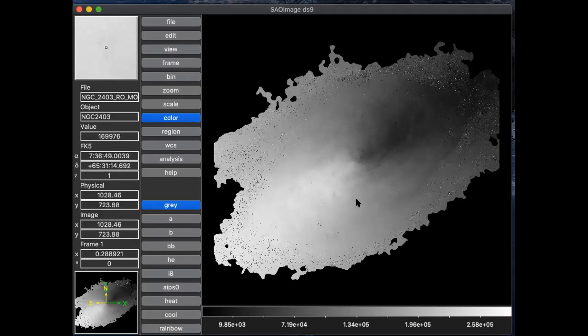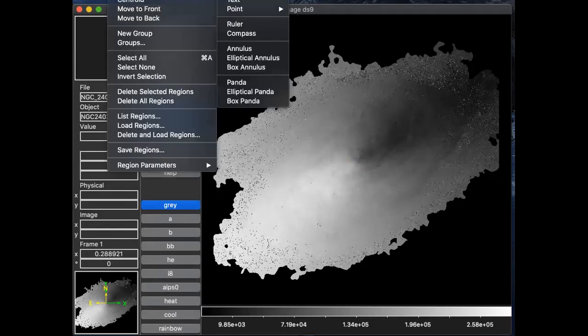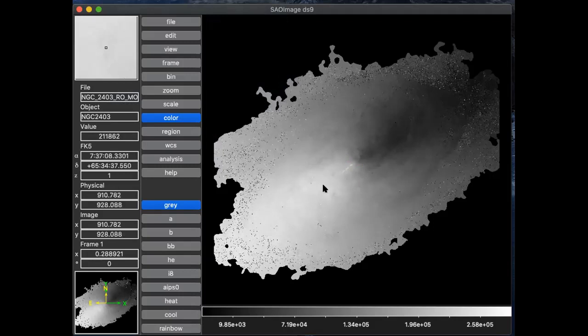The way you can check it is we can choose a line now and ask for the statistics along the line. So what it will do is calculate how the velocity changes along that line. So to do that, we go to region again and choose a shape which is a line and draw a line.